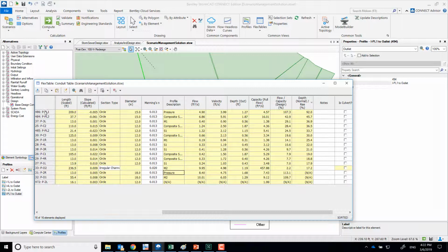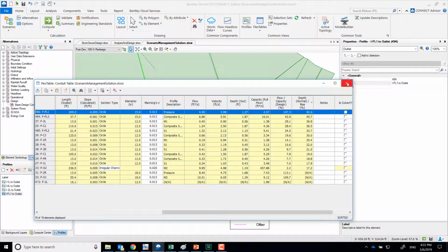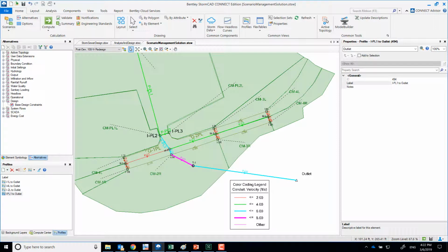Okay. So rational method is used to compute. The question gives you 3 different options. Peak flow from a catchment, average flow from a catchment, or a runoff hydrograph from a catchment. Calculate only the peak flow.